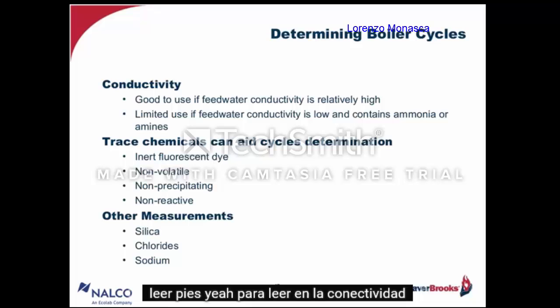And so if I'm reading in conductivity, I can get to TDS by dividing that number by 0.65. Excuse me, I've just got that backwards. I can use conductivity, and that is just TDS divided by 0.65. So if I multiply conductivity by 0.65, I get TDS. Probably confused you all based on that.